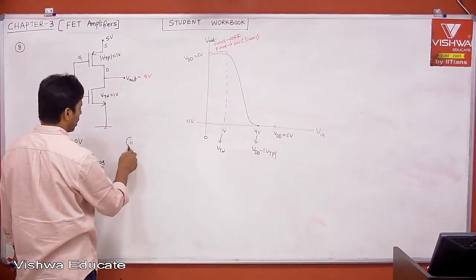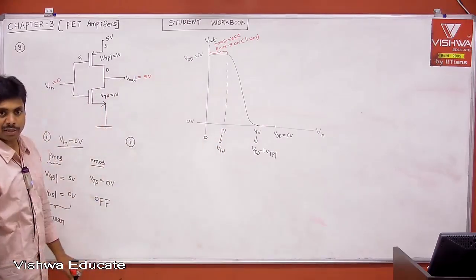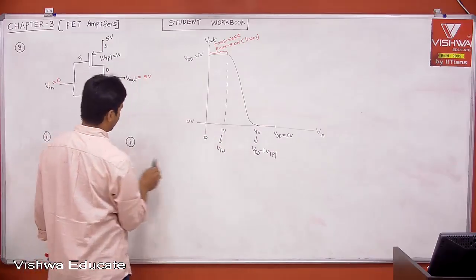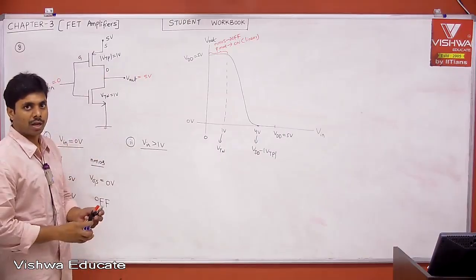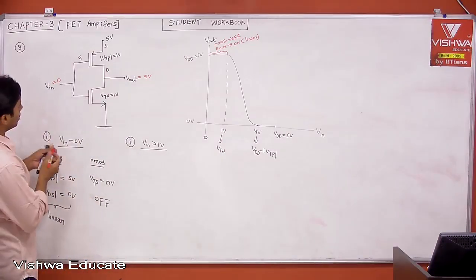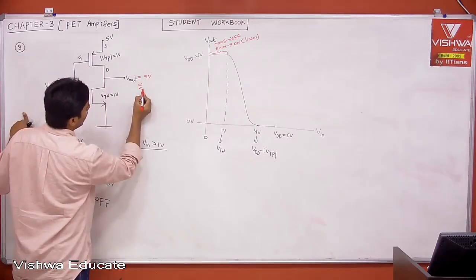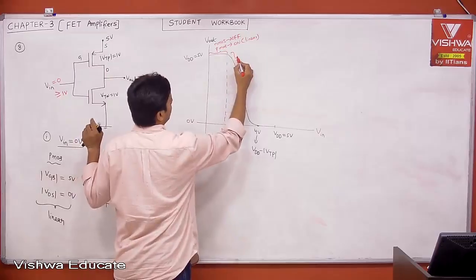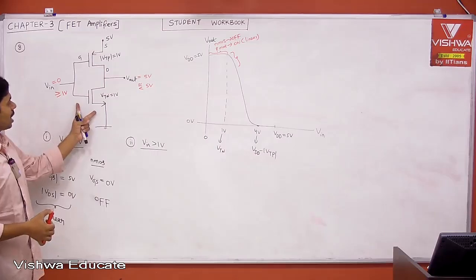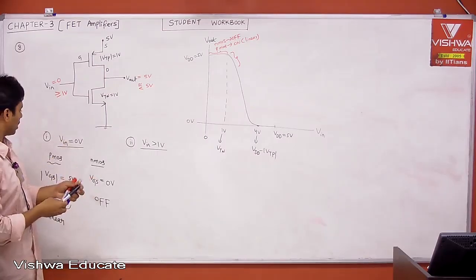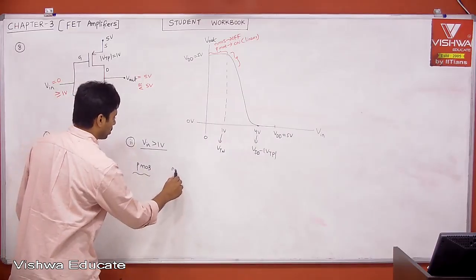Now case 2, as we increase Vin until you cross 1 volt, same region, same thing is expected. Let us say you are crossing 1 volt. When Vin is above or equal to 1 volt, then the output will be close to 5 but less than 5. I am speaking about that portion. Then you tell me what will happen. Your NMOS starts conducting. Let's see what is the PMOS state and then the NMOS state.